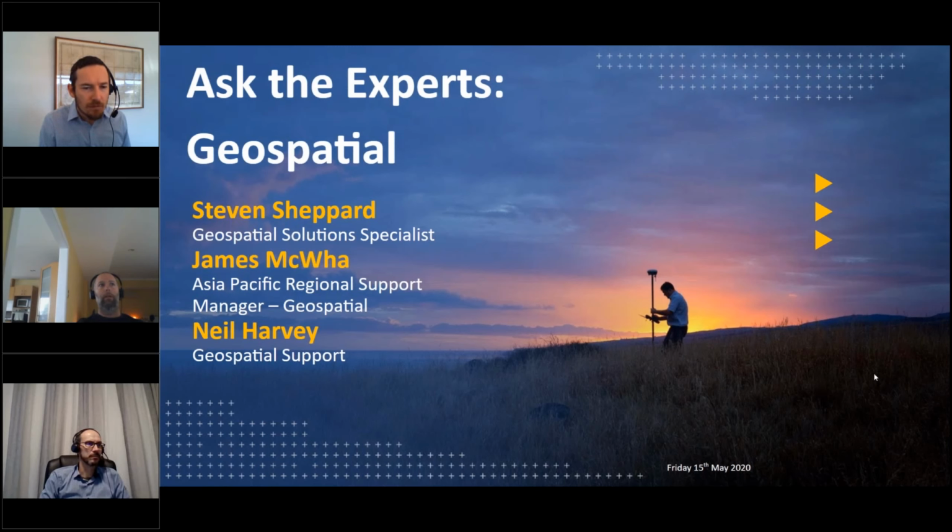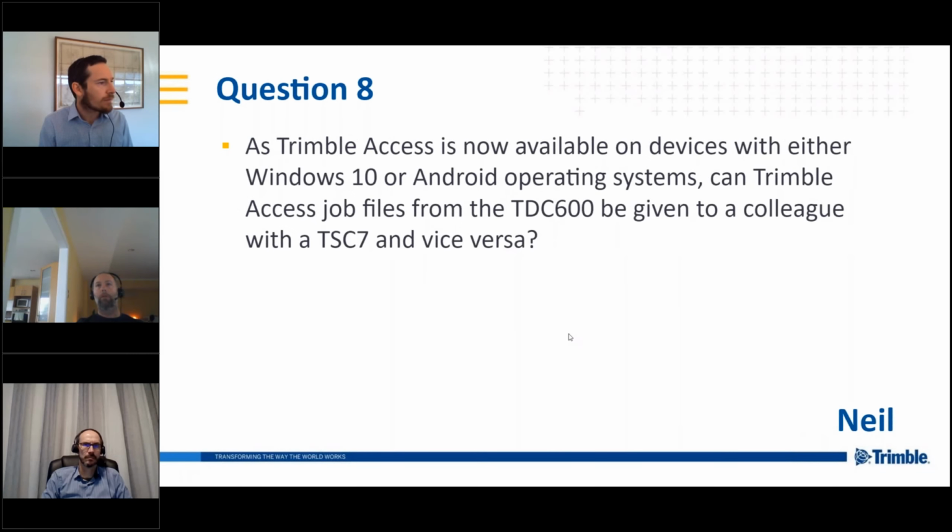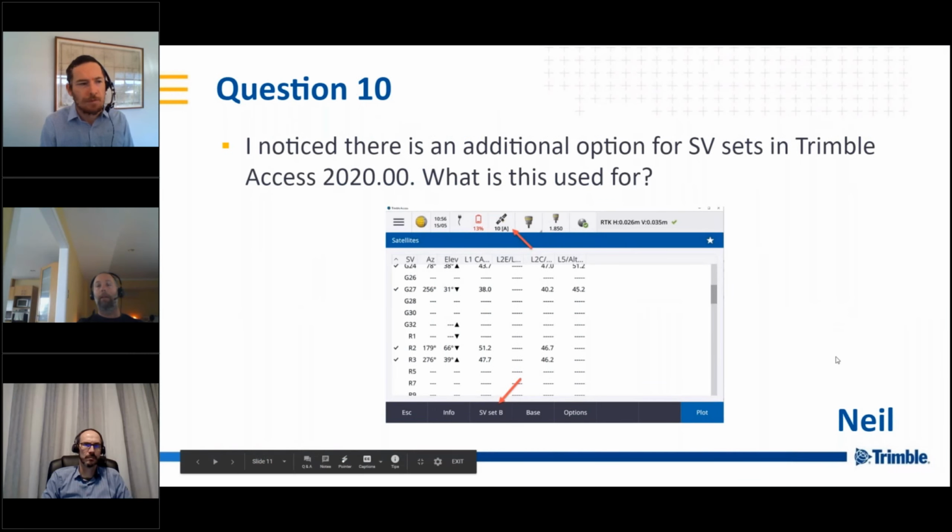Should I use this, or can I revert to a static datum, e.g. GDA 2020? So in Australia, the coordinate system has recently moved to GDA 2020. Historically, they've been using GDA 94. Now, the RTX use in Trimble Access up until now has always been using ITRF 2008 and then to Epoch